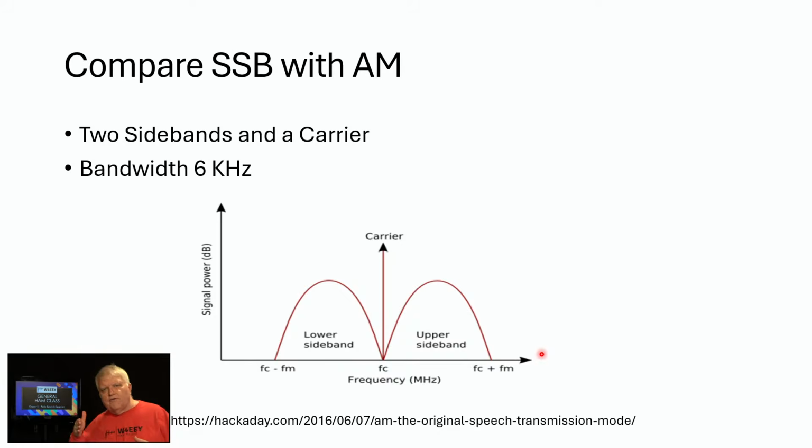That false carrier substitutes for the original carrier and then allows you to demodulate the single sideband signal. If you try to tune in a single sideband signal with a conventional receiver without a BFO, without being designed for single sideband, you won't be able to demodulate it, because it doesn't have a reference. You have to put that reference back in. Got it.